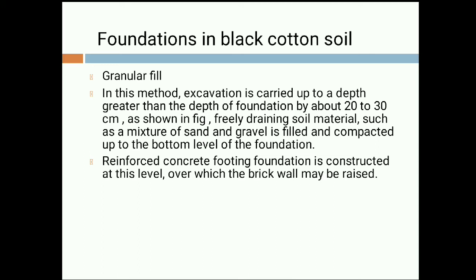Freely draining soil material such as a mixture of sand and gravel is filled and compacted up to the bottom level of the foundation. That is, the footing or the foundation will not stay in direct contact with the expansive soil and it will be in direct contact with the granular filling. We can also use reinforced concrete footing constructed at this level over which the brick wall may be raised. Means we can make such kind of vertical moisture barrier also.